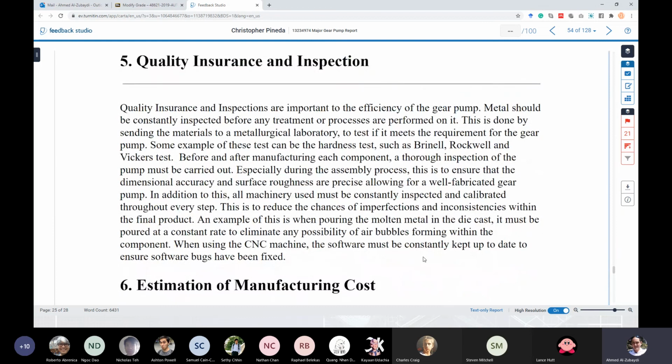But the first process we're going to do for the inspection is taking the main body, taking the cup, sealing them, plugging two of the outlets and pressurizing the third one and leaving it at higher pressure for a while to check if the main body is going to explode under the higher pressure or not. We pressurize it with water because water is clean, has a good viscosity and is an incompressible fluid.